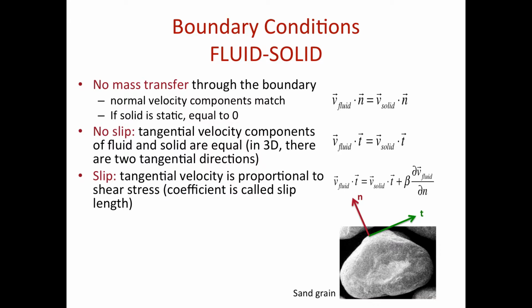There are various ways to define the slip length. In this case, there's this beta times the shear stress on that boundary. You could also view it as: my velocity is not 0 on the boundary, but somewhere inside the boundary where it formally goes to 0, even though I don't have fluid there. So the slip length could be thought of as how far inwards you need to go to zero out that velocity profile. It's not precisely the same as this beta, but to first order, those two things match. My point is that these are modeling solutions.